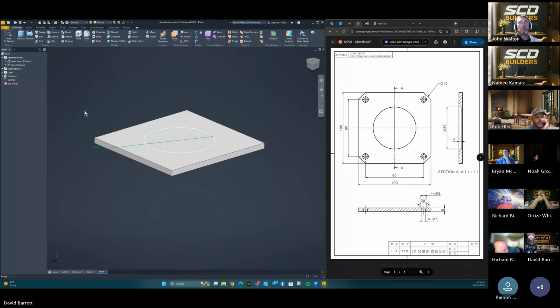You know how I told you to select the face last time? Here, I can only select the face unless I get on this circle right here. It's kind of hard to select another sketch that's on top of a sketch. So what I do is I go over to this model tab over here, go to sketch 2 and just highlight it. That brings up that toolbar again.